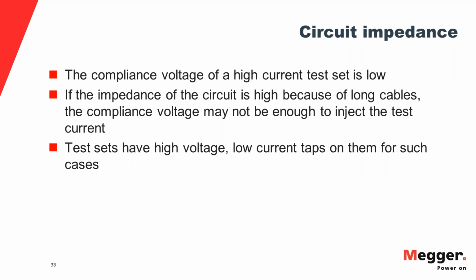So when you use these high current testers, these high current testers deal with really high current, but they have really low compliance voltages. If the impedance of the circuit is high, if you're using really long cables that can result in high impedances, then the compliance voltage may not be enough to inject the test current.